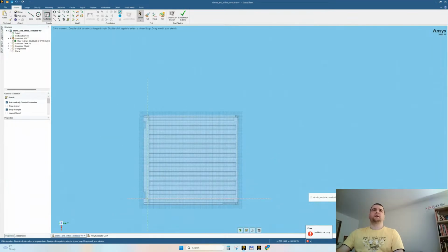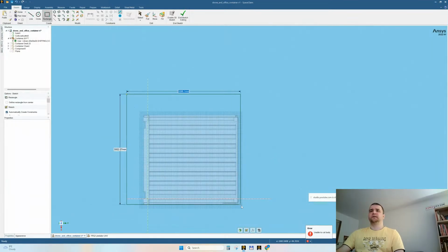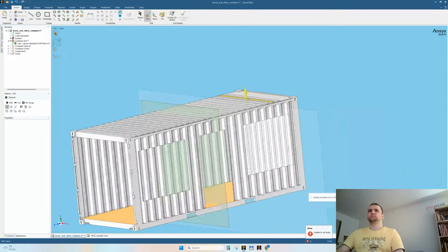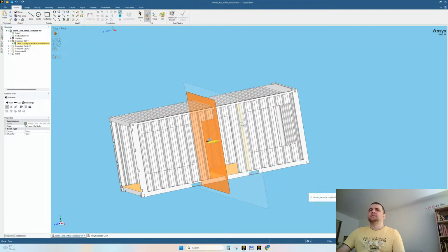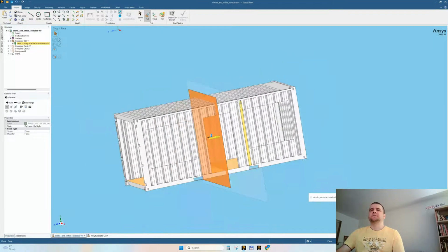Just for fun, can I create a rectangle big enough to cut this container with it? Cut here, and I will impose a negative, yeah, here on this side. Minus, we don't care. It can be 50, 100, 1 millimeters. I want to create the smallest. Cut.